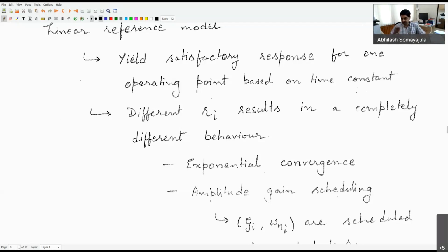I may say that up to a certain amplitude, I'll go with certain damping ratios and certain natural frequencies. But if I'm giving much higher amplitudes, I know that will result in unphysical velocities and accelerations. So it makes sense for me to use higher dampings and a different set of natural frequencies for those higher amplitudes. Okay, so that is one methodology to deal with the fact that the velocities and amplitudes which we are getting may not be commensurate with reality.